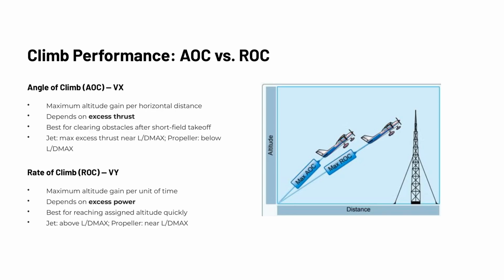The key takeaway is that AOC and ROC are not the same thing, and they are not achieved at the same airspeed. Knowing which one you need and why directly impacts both safety and efficiency in climb operations.